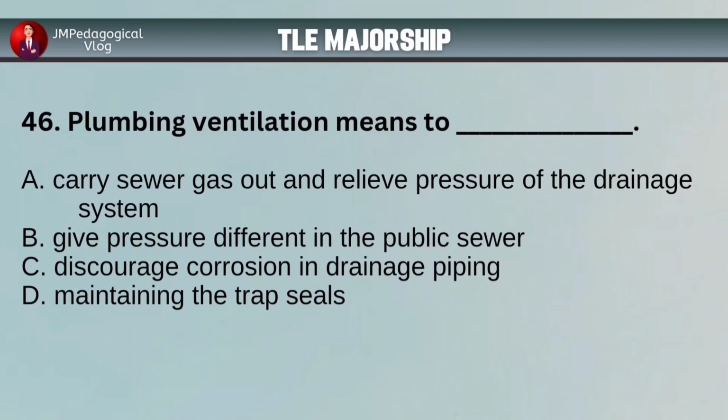46. Plumbing ventilation means to a. Carry sewer gas out and relieve pressure of the drainage system. b. Gives pressure differently in the public sewer. c. Discourages corrosion in drainage piping. d. Maintaining the trap seals.